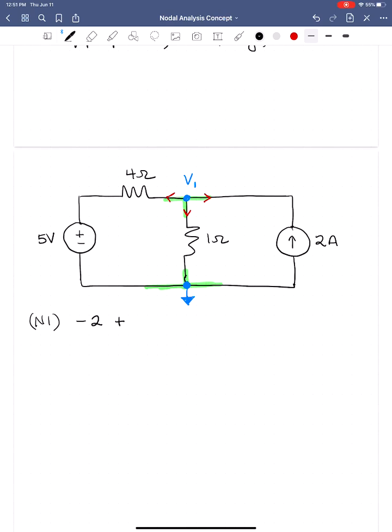The current flowing down, this current here, is through a resistor. So we know that we need the voltage drop across the resistor, and we divide it by the resistance to get the current. We have the resistance, which is 1. So what we need is the voltage drop across this resistor. And here's where those node voltage variables are going to come into play. Let's talk for just a second about what we want to solve for. We want to solve for the voltage drop across this resistor.